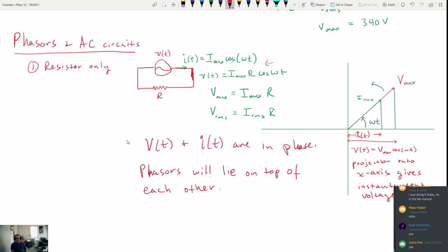I'm not saying anything groundbreaking or new, because obviously if you draw a circle in the xy plane, like the unit circle that you learned about, then a vector drawn from the center out to the circle will always have components given by something cosine theta and something sine theta. So this is just the nature of how vectors work. But what makes it a phasor is the fact that it rotates in this space.